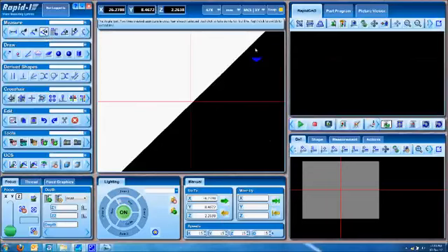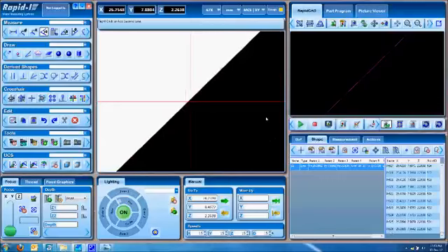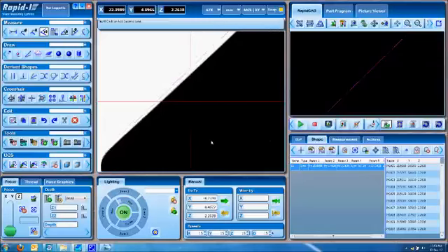So in this we want to measure a simple angle and a corner radius. Choose the angle tool, click and click. You get an automatic edge detection within the blue box, and it's taken about 500 points. Done, the best fit. You go to the end of the straight edge, click again to define another region of interest, and the line gets automatically extended.